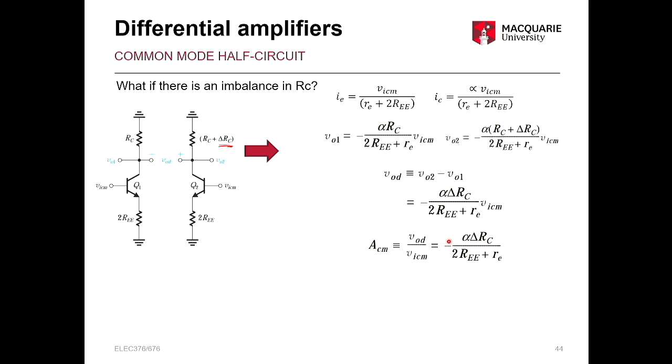And again, very similar to the MOSFET, we can see that the gain in the common mode, which we want to be 0, is going to be very dependent on that change in RC, that mismatch, okay? That completely affects it. Assuming that can't be avoided, you have some mismatch, then it's the emitter resistance that will dominate the value there. Okay. So if you were given a mismatched circuit and asked to maximize the gain, assuming you can't change the RC values, then those are the values you need to change, okay?